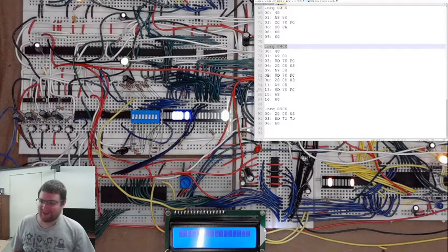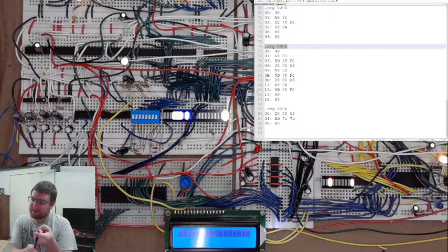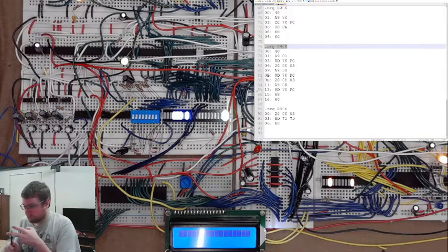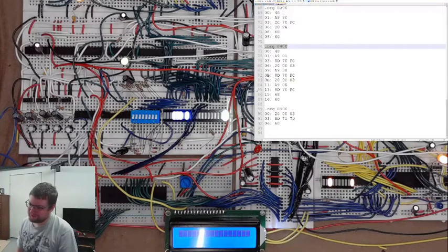And your CPU will just have to waste those 8 clock cycles doing something else. And if you're using that time to read the next byte that you want to send, to read it in, and then you adjust your pointer as well during that time, that's at least 4 clock cycles right there, probably 6. And then you jump back in your loop. There's another at least 2, probably up to 9. Your SPI is already done by the time you get back there. So there's things you can do to have a very efficient SPI where it's almost like reading off of RAM.